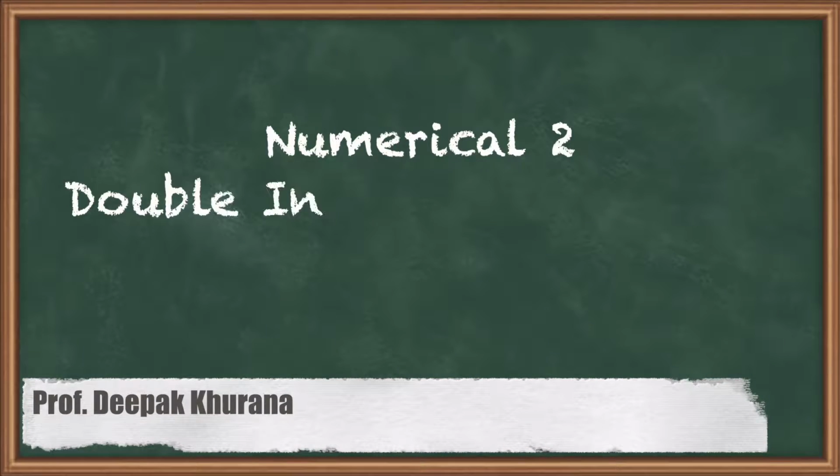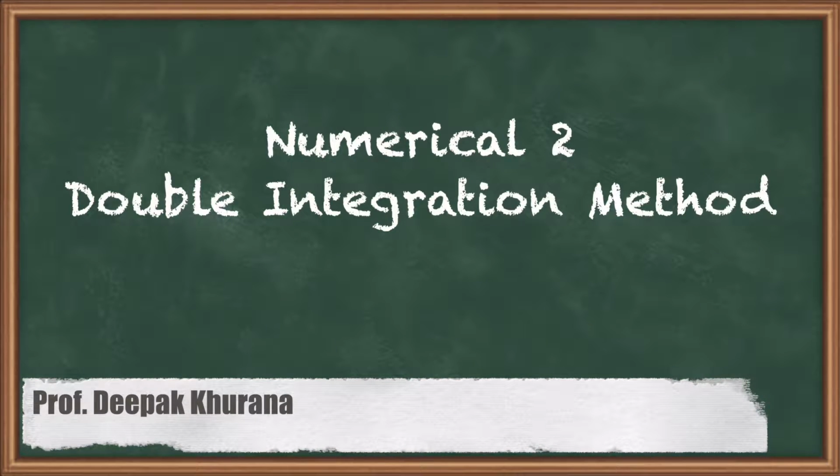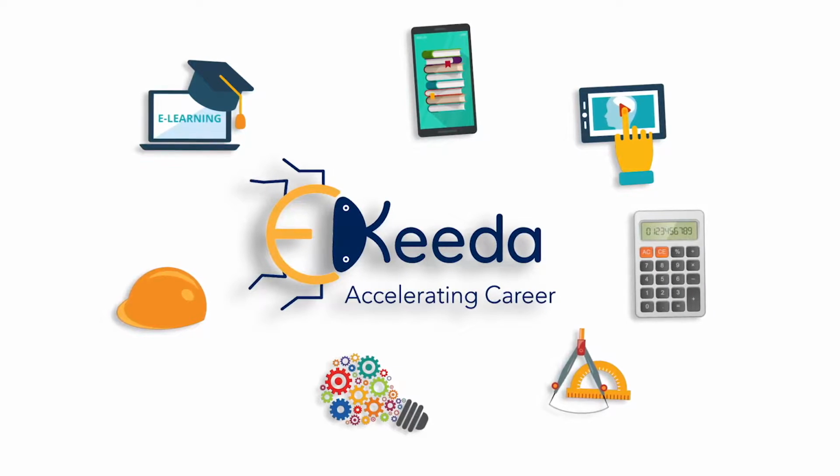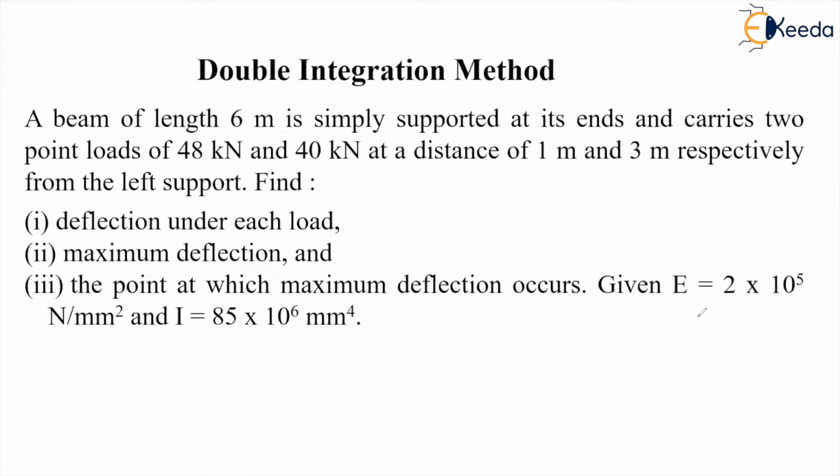Hello dear students. In this session we are going to solve a numerical on the double integration method. In this question we are given a beam of length 6 meter, simply supported at its ends, which carries 2 point loads 48 kN and 40 kN at a distance of 1 meter and 3 meter respectively from the left support. We have to find the deflection under each load, the maximum deflection, and the point at which maximum deflection occurs. The modulus of elasticity and moment of inertia are also given.